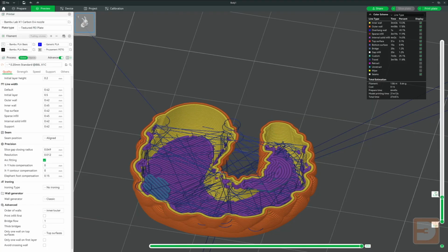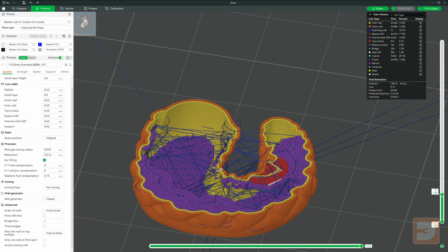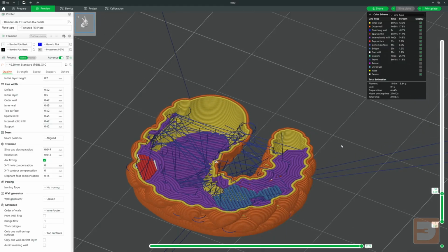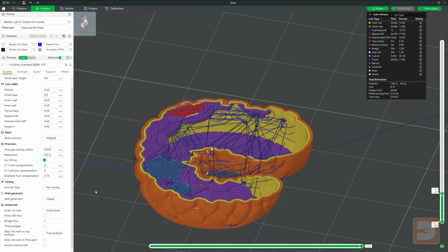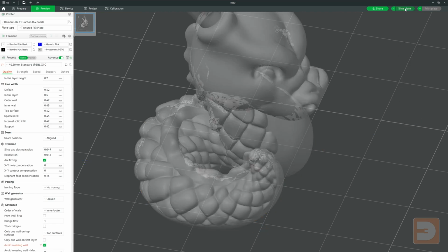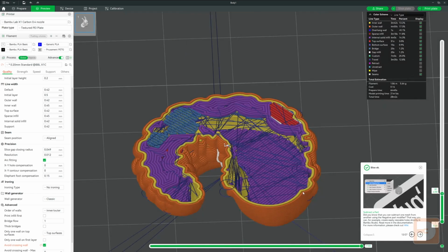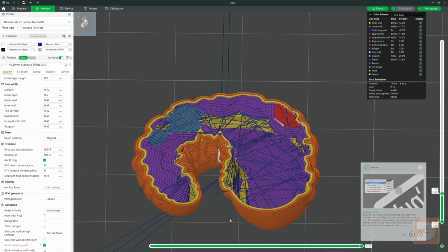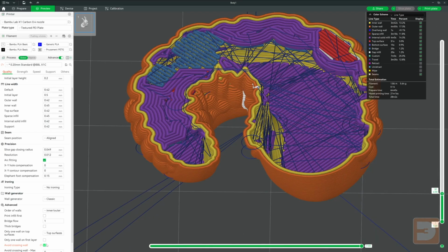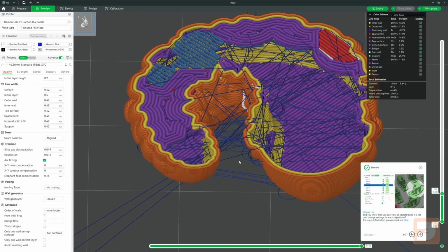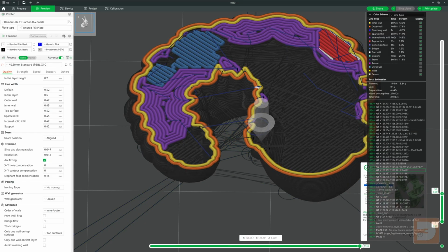This is the movement that the nozzle will be making in areas where it's not actively extruding. If retraction settings aren't spot on, or if your filament isn't playing ball, you can find that thin strands or strings can be accidentally printed when the nozzle follows these paths. With this feature turned on, it tries to avoid travel paths which involve crossing over exterior walls as much as possible, as if stringing occurs within the exterior walls, you're never going to see it once the print is finished.